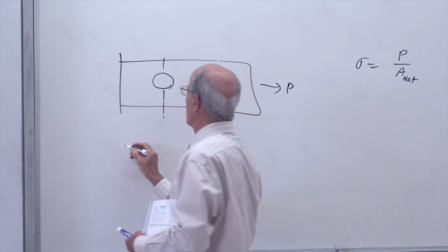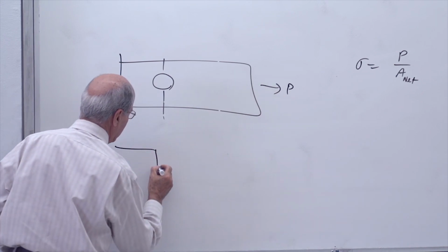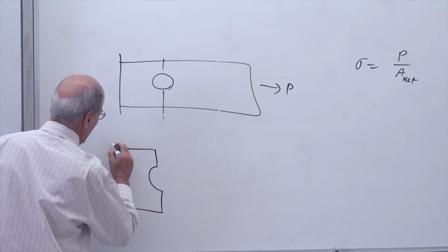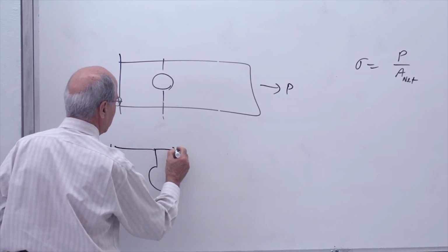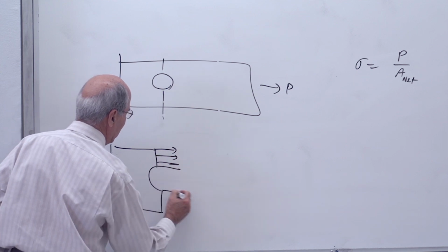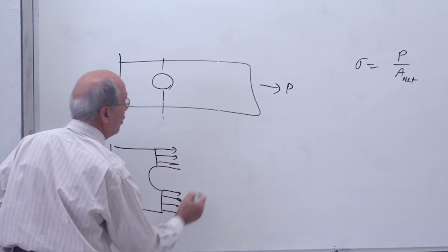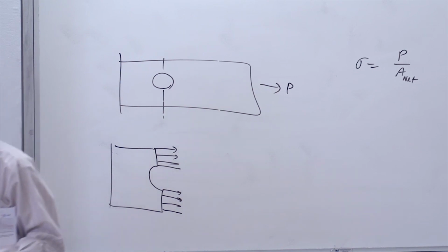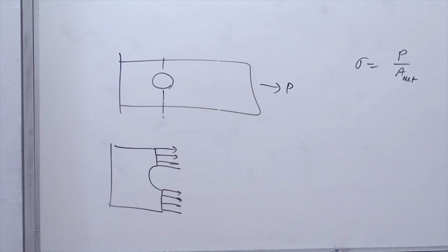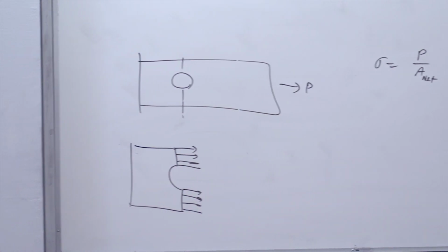So in other words, you should understand that in this area, when I put it under tension, this is sigma average. The sigma average is equal to force over the net area. Is that correct? We have done it in chapter 1. That's how we did it theoretically.